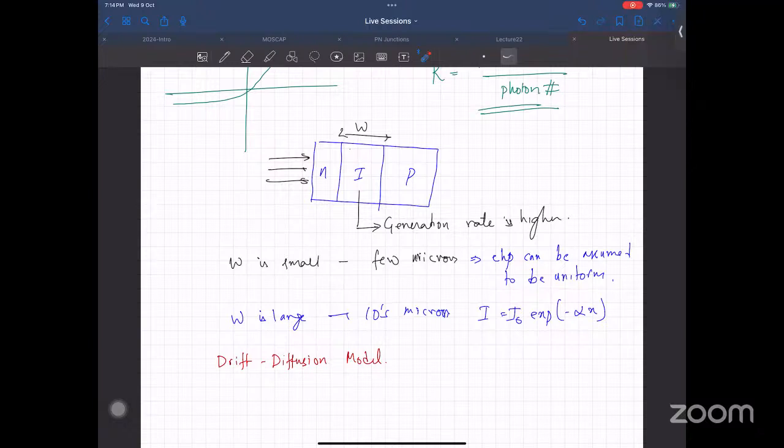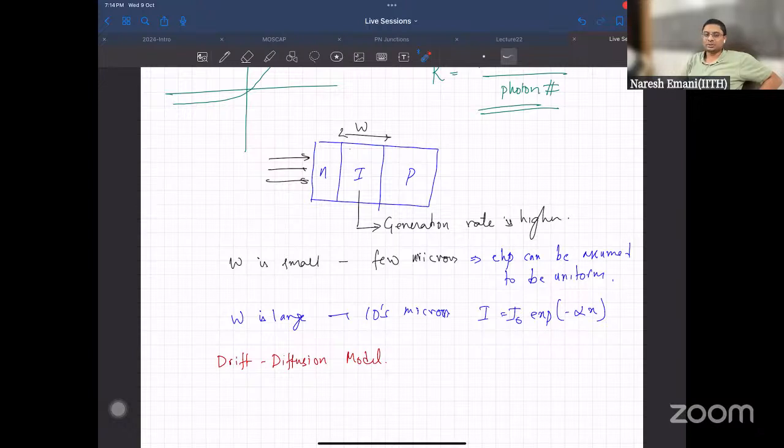But practically, a large width is desired in photodiodes, because you get more absorption cross section. The issue is that with large widths, the response time suffers. There are multiple things we have to optimize for. You want the carriers to move to the terminals as quickly as possible. Let's say you want to operate a photodiode on a picosecond timescale. But the carrier has a certain velocity, a certain electric field and a certain mobility, so the velocity is going to be limited.